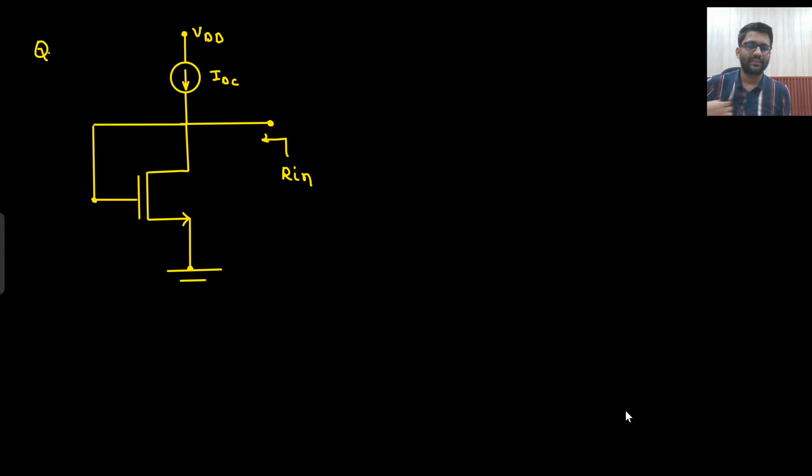Let's get started. Do this question on your own. You need to find the value of Rin. I will take a pause. You try doing this question on your own. How will you find Rin? This IDC and VDD are both DC bias, so what will happen? This will be gone. Now find Rin. You should be able to find it.